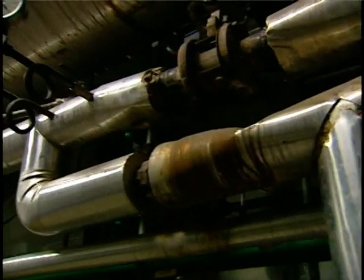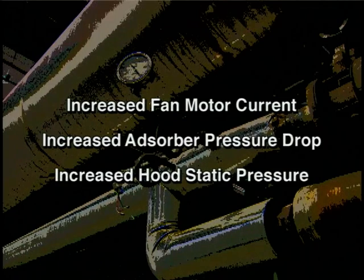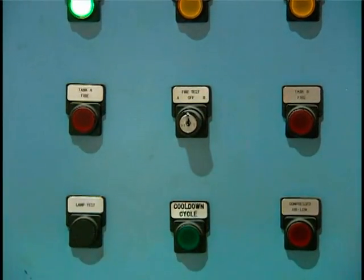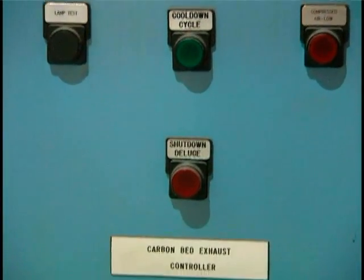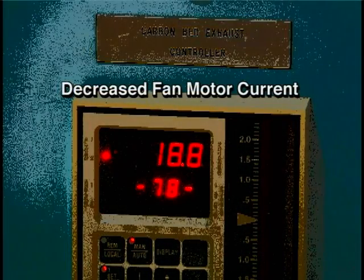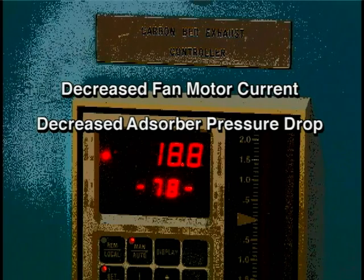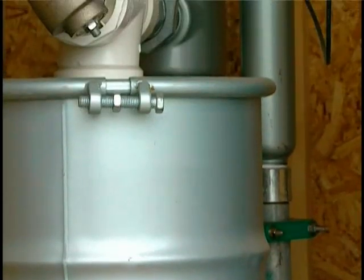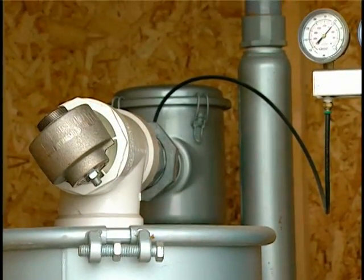Gas flow rates above the design range of the adsorber can potentially lead to breakthrough. An increase in the gas flow rate is indicated by increased fan motor current, increased adsorber pressure drop, and increased hood static pressure. Decreased gas flow will result in reduced capture of the contaminants at the source, resulting in fugitive emissions. A decrease in the gas flow rate is indicated by decreased fan motor current, decreased adsorber pressure drop, and decreased hood static pressure.